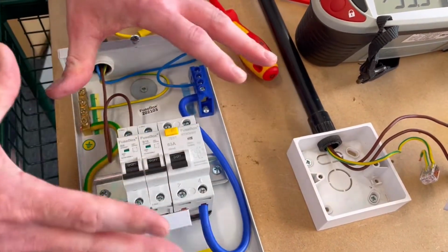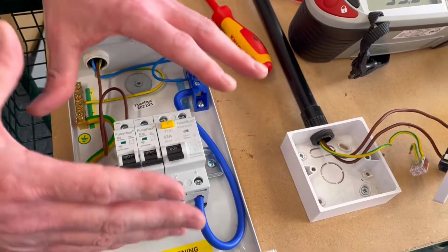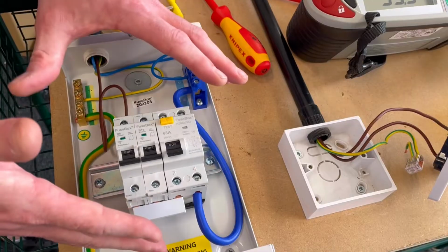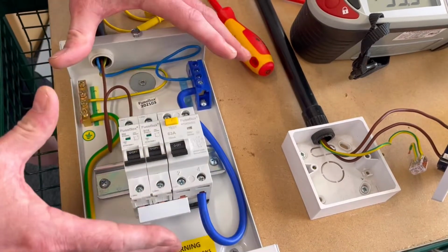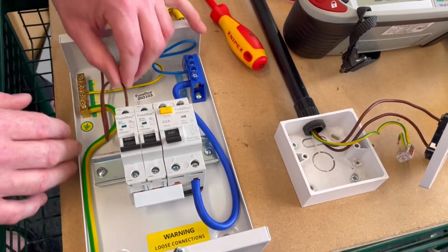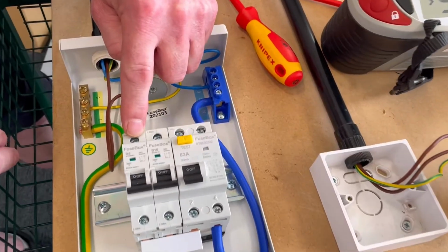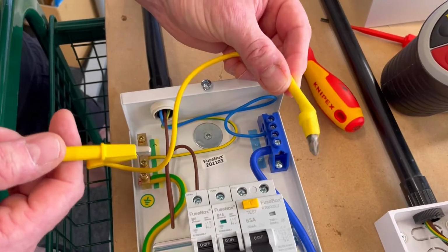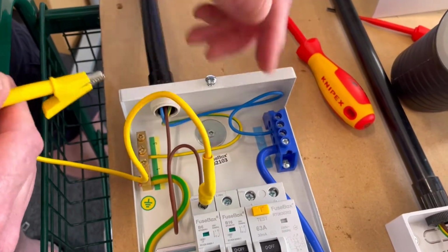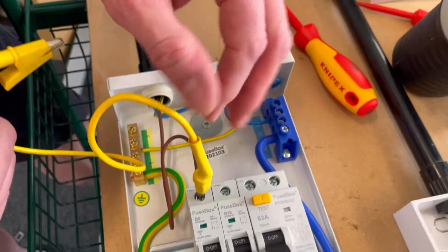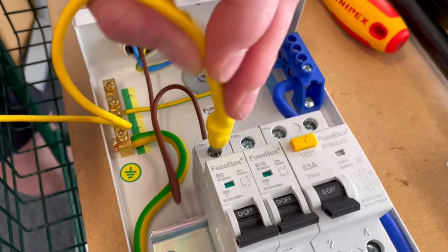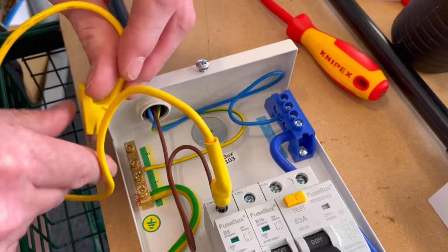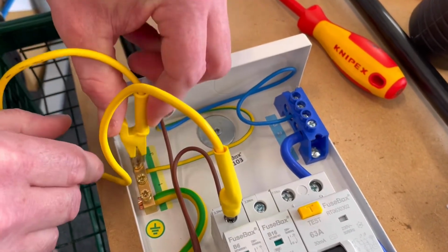So if it was, of course, there'd be the safe isolation procedure and loads of other stuff we discussed on the channel. But this is a test that we carry out really early on in that first 10 weeks. There's no electrical energy in here and it is a dead test. So I'm going to link between the top of the circuit breaker and the earth bar, and this is where this R1, R2 link comes in handy, because this one here is magnetic. So you can see there, if I just drop it on, it just drops onto there, and then if I get it in position, it just sticks into place. So that's connected, and we can link it to the earth bar where our CPC is connected.